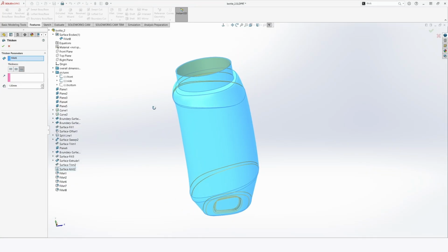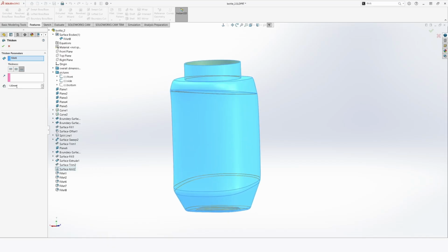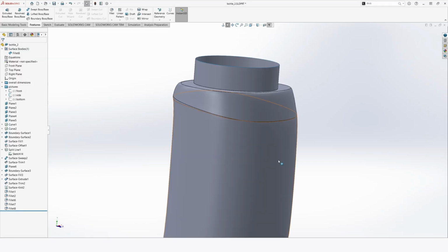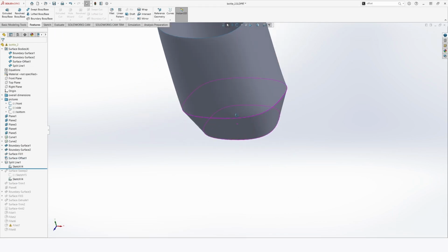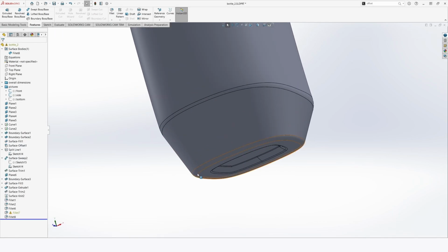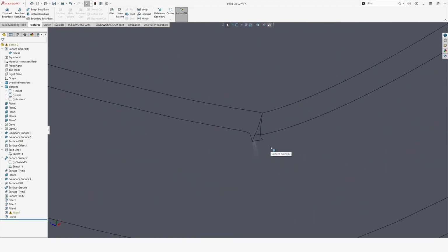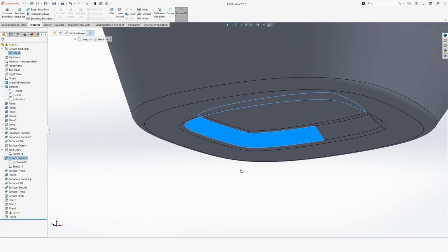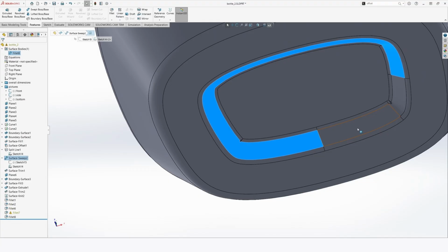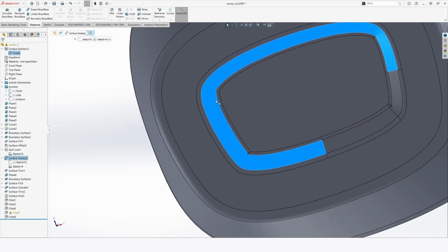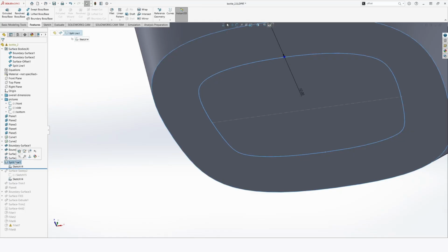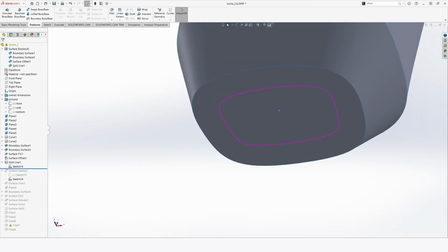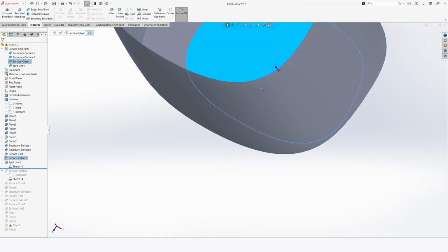It says face with the fail check. All right, this is a good learning opportunity. So we'll see how to troubleshoot this. So upon troubleshooting, it seems like one of the issues might be that these faces are not too clean. Doing the swept face around this sort of irregular profile was not too good. So what I can do is come back here and redo how I implement this exactly.